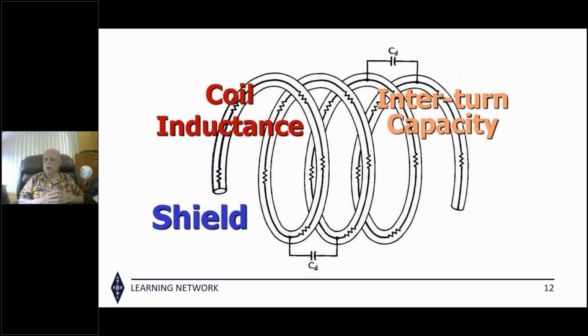But yeah, sure. Well, anyway, a rain gutter antenna is usually a non-resonant antenna. So chances are you can tune it up with a 49-to-1 balun or 7-to-1 balun, or, it's a non-resonant piece of wire. There are lots of ways to tune it. So I don't think there's a categoric answer to that.